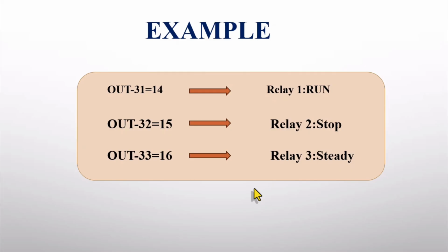Steady state means that you have given a frequency command to the inverter. For example, 30 Hz. The inverter has started up, ramped up from 0 to 30 Hz and is now running at 30 Hz. It continues to operate, meaning it is working at 30 Hz. This mode is called steady state.